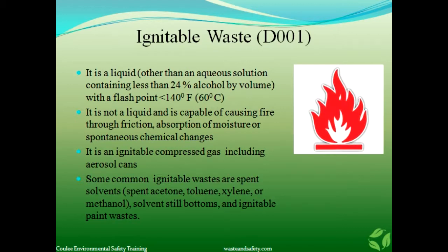Compressed gases can also be considered ignitable waste. So your old compressed gas cylinders or old aerosols, most often, can be considered an ignitable waste if they have certain properties, such as if they are flammable in the air, if they're a mixture of 13% or less, they have a flame that can project more than 18 inches from the valve when it's fully open, or if it can flash back to the valve itself, or there's any kind of significant propagation of the flame away from the valve or ignition source if it's open.